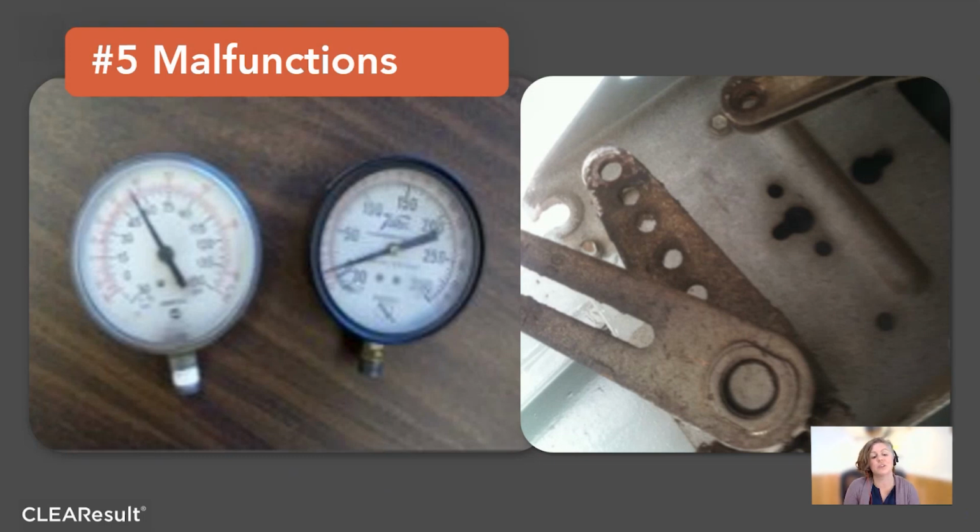The signal that they're giving is not going to give the right information to you, and your system will not be operating correctly. Also, the linkage for the economizer here, there is no linkage, right? If the software gives a signal to the economizer to open, no way that's going to open, not without the mechanical linkage. So malfunctions can be a big waste of energy. If you don't know, you can think things are operating, you can think all the signals are coming in and your system is operating correctly. But with a malfunction, you just never know, and you're not getting the right efficiency.